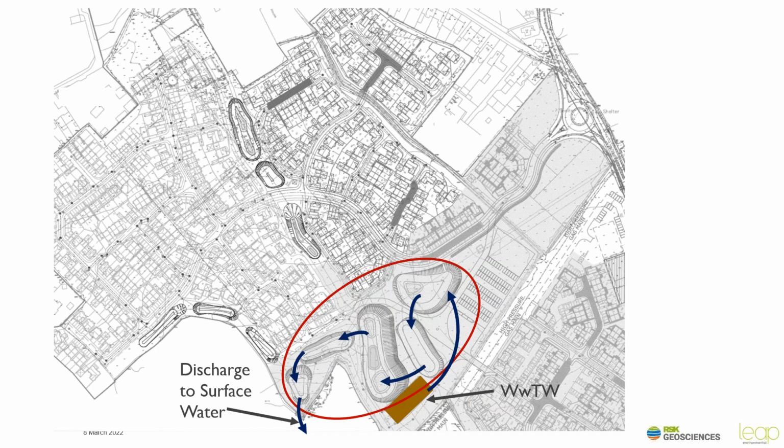The wastewater treatment works will cope with the loadings and achieve the requirements of the environmental permit. But that discharge won't still be good enough to achieve nutrient neutrality, which is an interesting conundrum, since you've achieved environmental permit requirements, but not sufficient reduction for nutrient neutrality.